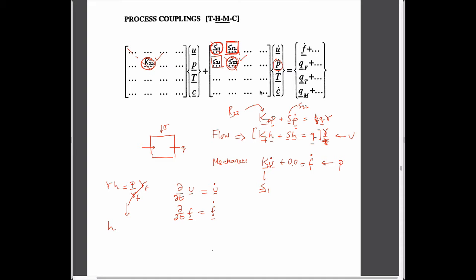And then through what we've done, we've allowed the displacement equation to include the effects of fluid pressures, now in this expression. So it includes not only displacement terms, but also fluid pressure terms. And in the flow equation, which previously only included fluid pressures, we now have something that includes deformation. And so those cross terms are the linkages that we have.